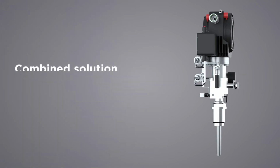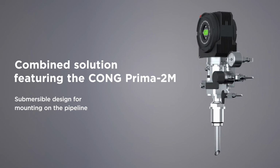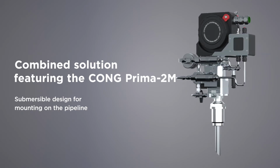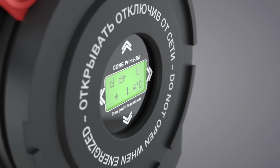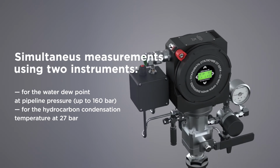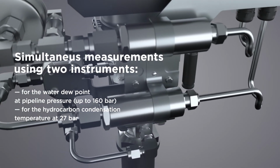Vympel has developed a solution that provides for water dew point and hydrocarbon condensation temperature measurements, comprising a combined system with Prima 2M analyzer mounted directly onto the gas pipeline. Measurements are taken automatically in alternating mode. One mirror and one optical system for both measurements. In this way, the device performs the function of 2 analyzers, one of which reports measurements at the operating pressure in the pipeline, and the other at a pressure of 27 bar. The pressure requirement for measurement at 27 bar is achieved by means of a pressure reduction system.